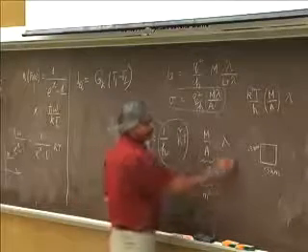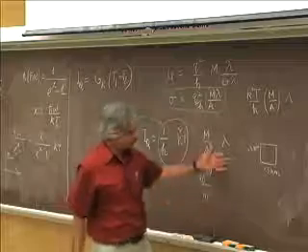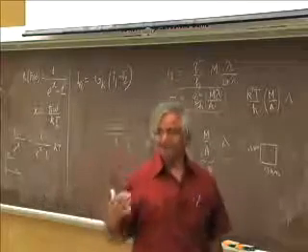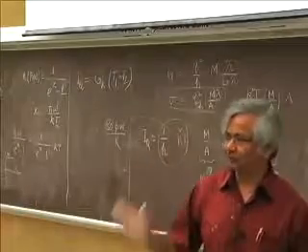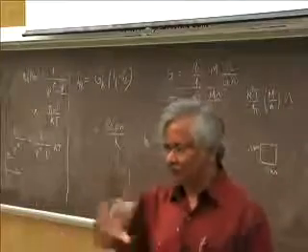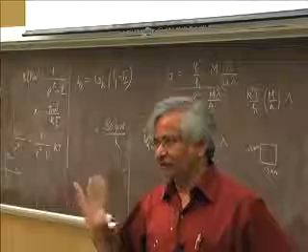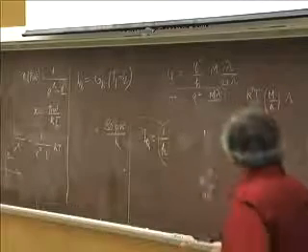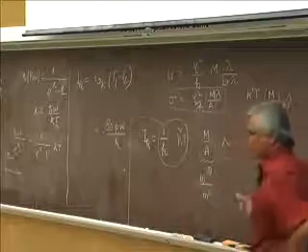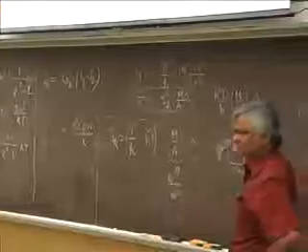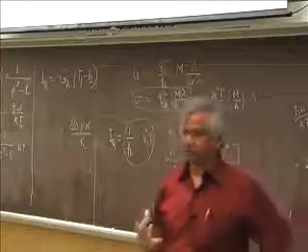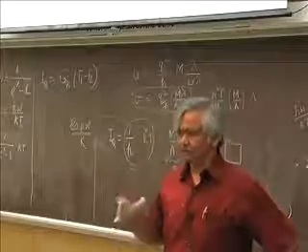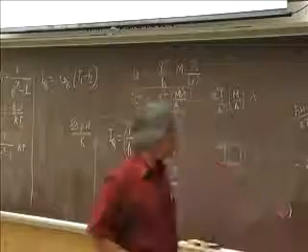And the mean free paths for phonons vary widely. With thermoelectrics, you really want to cut down the thermal conductivity, because it gets in the way there. The best ones are usually those with very low mean free paths, because of various grain boundaries or other reasons inside.